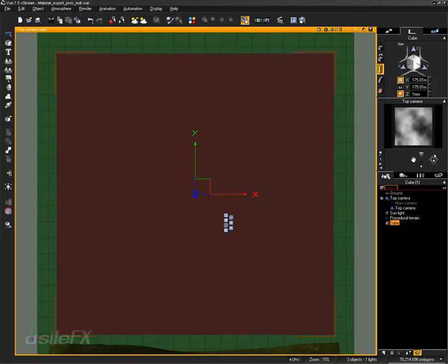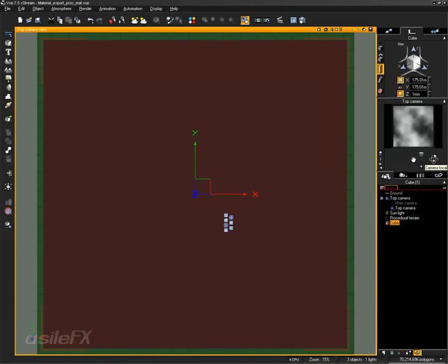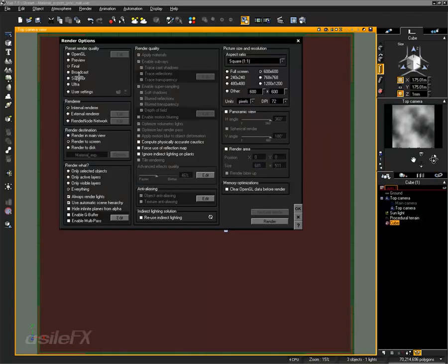Another more helpful method is to zoom out a little more or move the camera back a little more and then use the top camera focal zoom option to zoom in, and that will remove more distortion. So all you have to do now is select the size you want to output. This will also render very quickly.